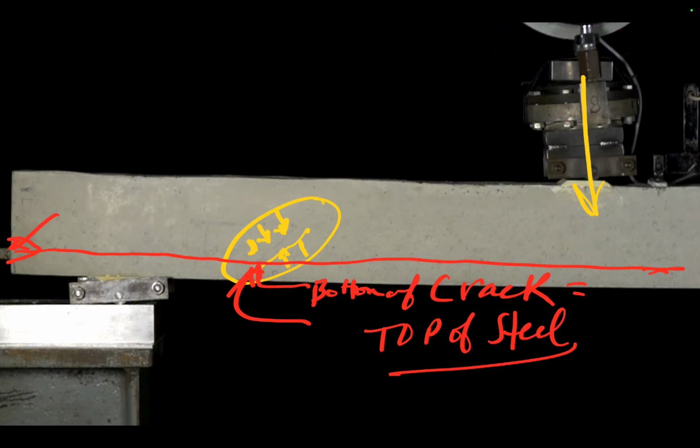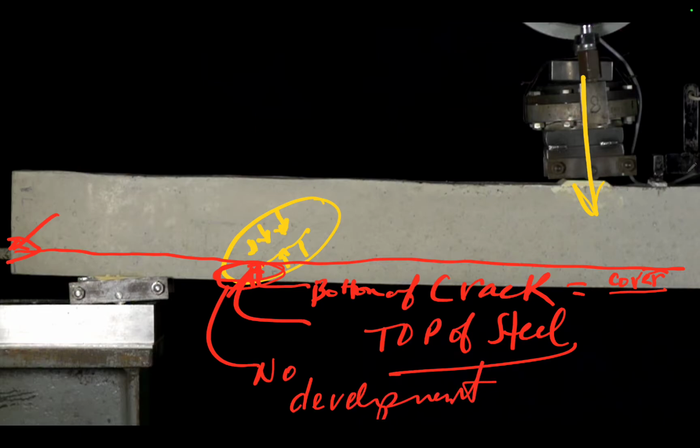The cover, this is the cover, the lower part below the steel. The concrete cover. At this point, there's no development of the crack below it. No development that I can tell of, right? And then the crack stops here. All right, so it stops there. So from here to here, this now becomes your tension. Crack. It's tension. It's opened up. Tension created it. And from here, this is your neutral axis. Okay. And this is your compression zone.